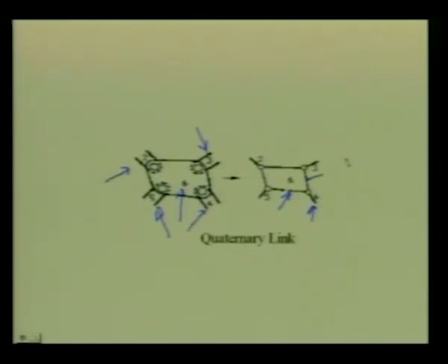To avoid this ambiguity, we should hatch this link number 6 to represent that this is a single rigid body and this is a quaternary link connected to 4 other links. This diagram shows how to represent a linkage where there is a prismatic pair.